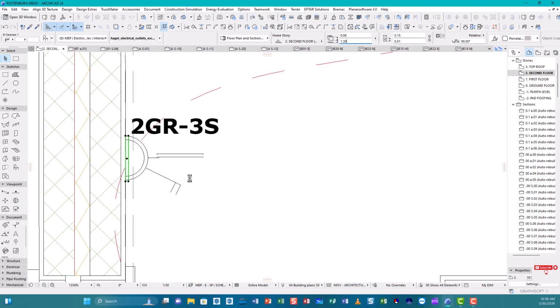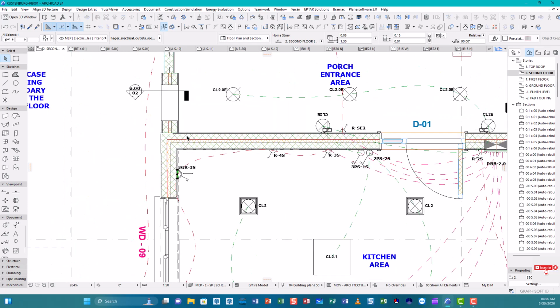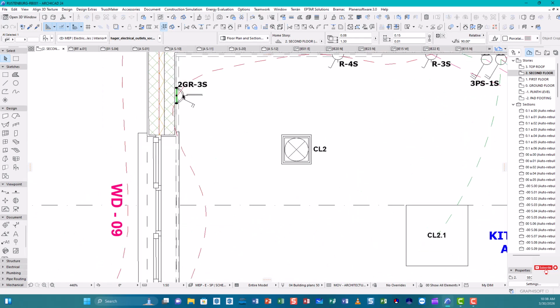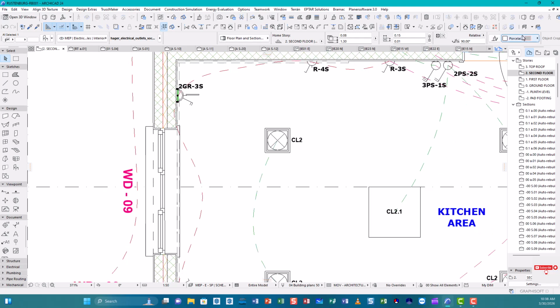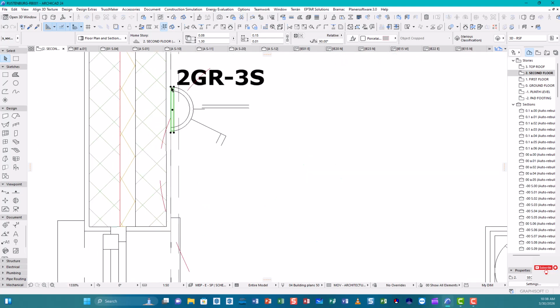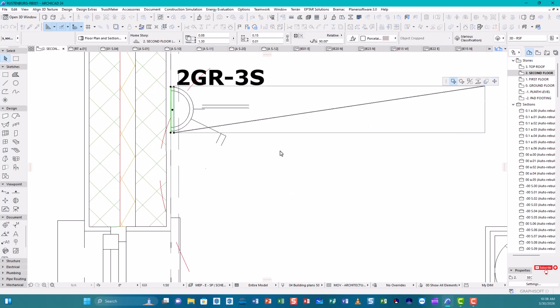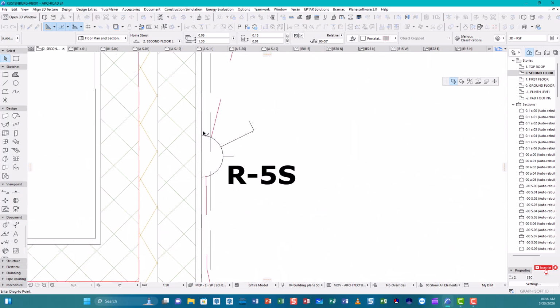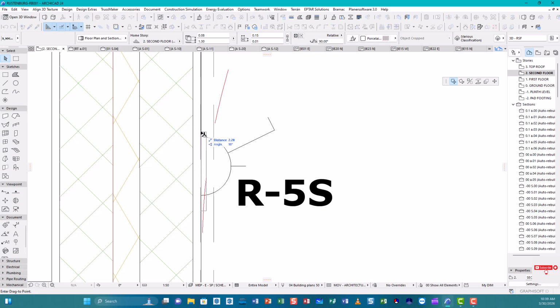So I'm gonna copy it. The 1.3 there, because I know all these sockets. We have 3 there. We have 1 here. What I can do, because if I go to the identification, it says receptacle, so it's not a problem. So instead of going back to pick another socket, I will just copy the one that I have here, and bring it all the way down, closer to this single one, somewhere here. Click, create a copy, and click once there.